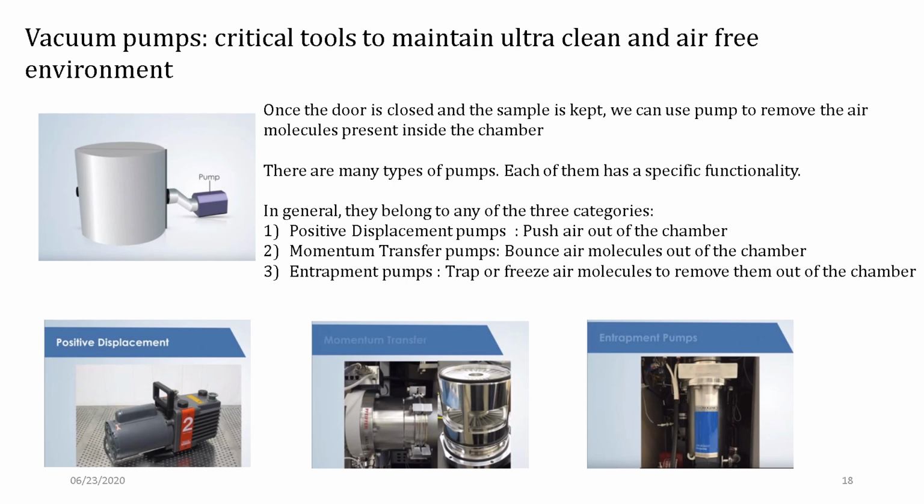In general, there are three categories. One is called a positive displacement pump, which just pushes air out of the chamber. Then you have momentum transfer pumps, which bounce air molecules out of the chamber. And then there are entrapment pumps, which trap or freeze air molecules to remove them from the chamber. All three ultimately reduce the pressure inside the chamber, but the way they do it is different.